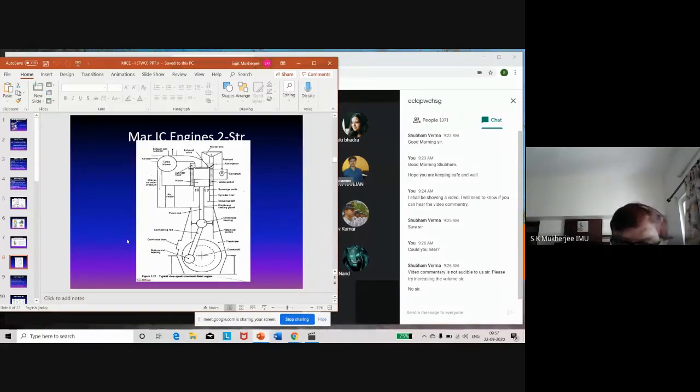And the last but not least, you may have a fantastic bearing, you may have fantastic lube oil, you have all the clearance, but you cannot afford to load the bearing more than its designed load. An overloaded bearing will fail. So that load has to be within certain specifications. All right. So these are the 4 factors. If you want, you can write it down.